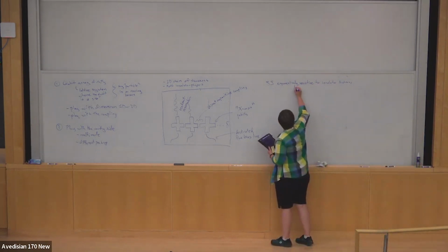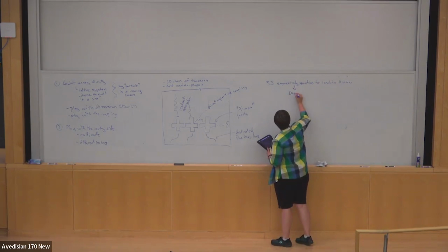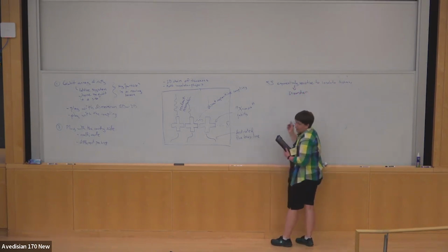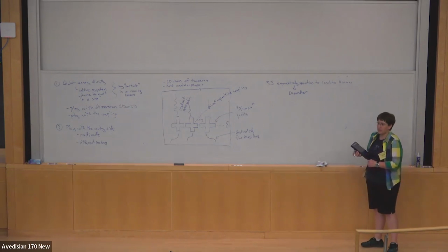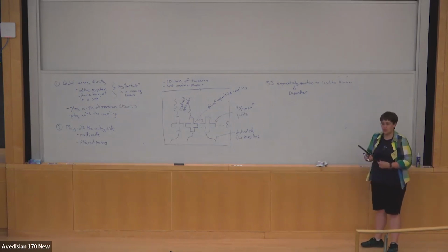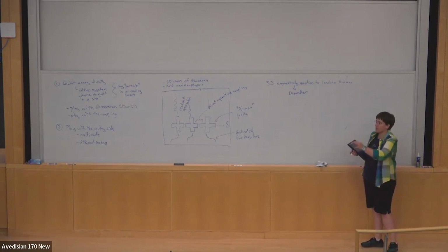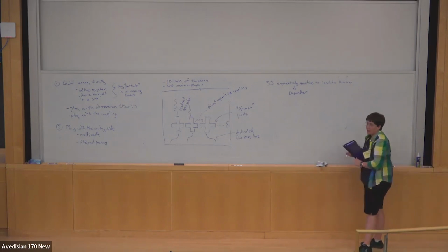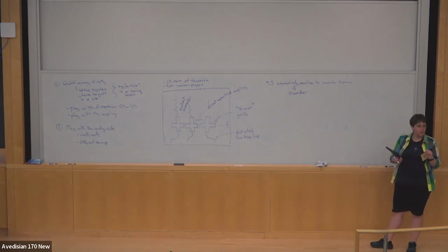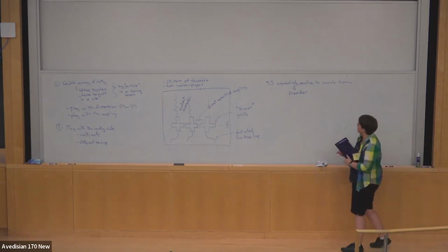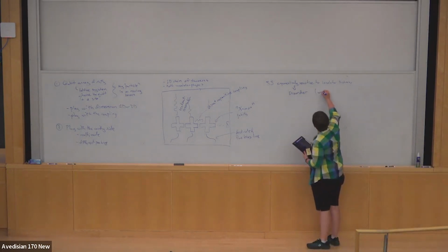The corollary to that is disorder. It's essentially impossible to make 10, 20 Josephson junctions or even 2 Josephson junctions that have exactly the same EJ. You make them the same area, you run them through the same recipe, and they aren't exactly the same. This is the reality of life in this regime. Welcome to solid state.